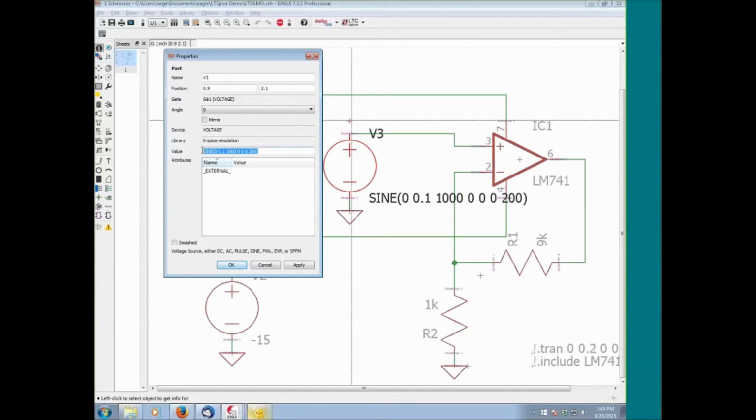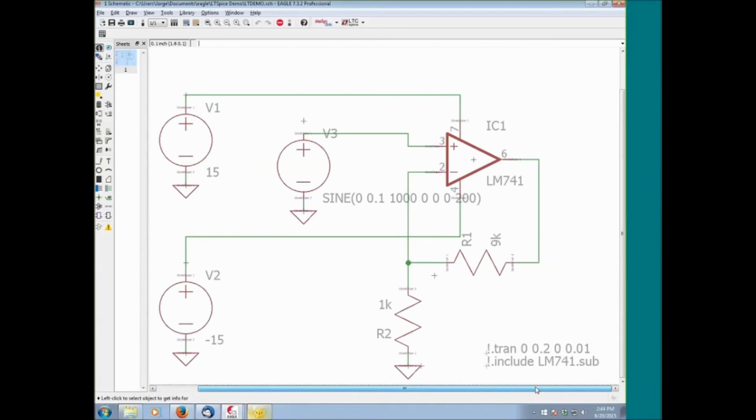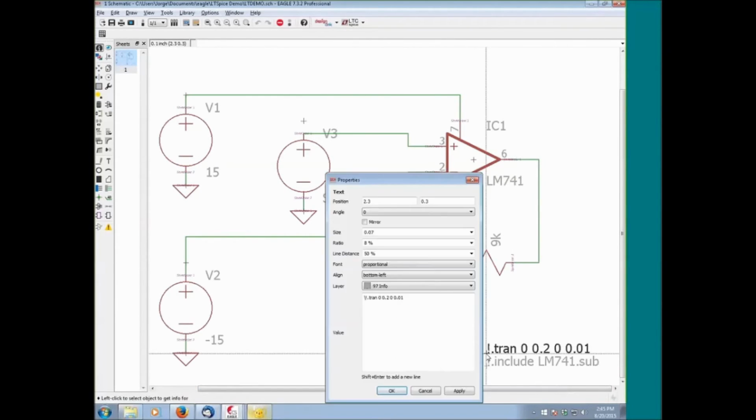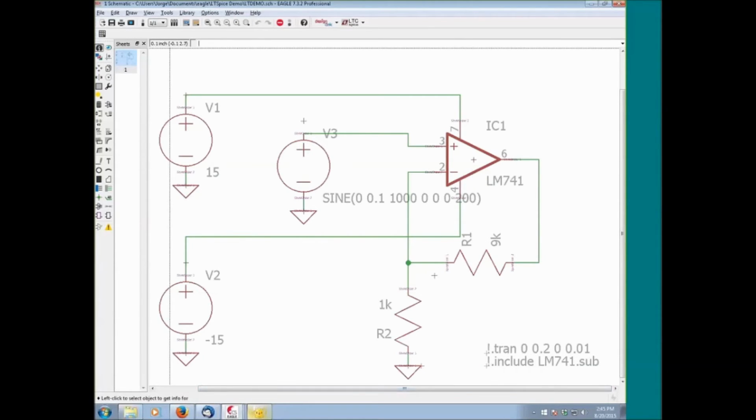This value line I got comes from basically following the same syntax as LTSpice would follow. Same thing here. If you guys look over here, these lines of text, the way LTSpice interprets some text as a spice command is by us escaping with the exclamation point. If you do that, it'll interpret it as being a directive, a spice directive, okay? You okay on that? Go back to the control panel.